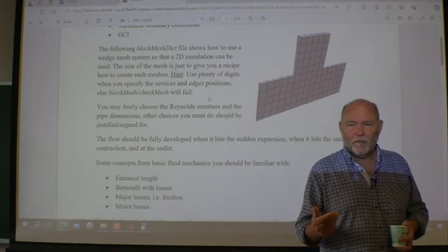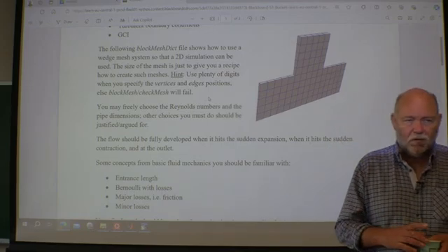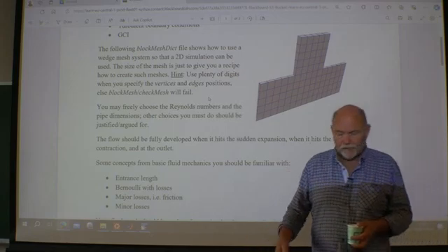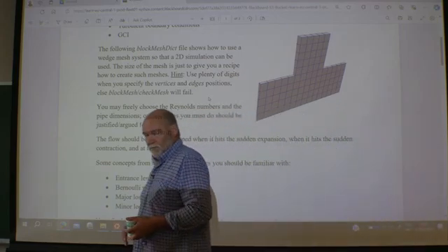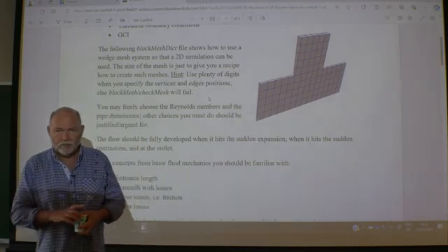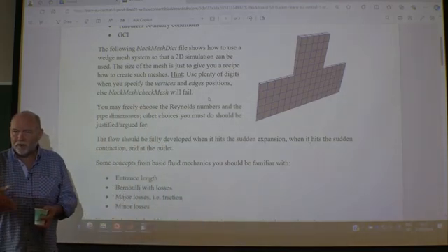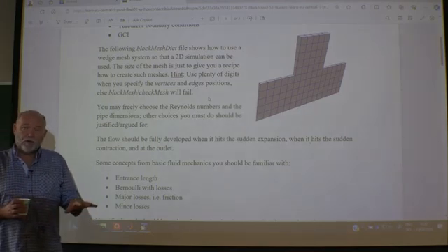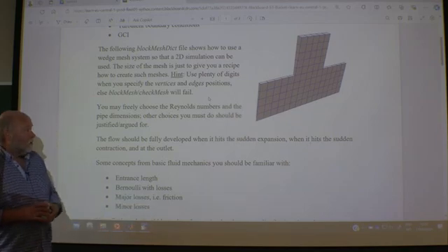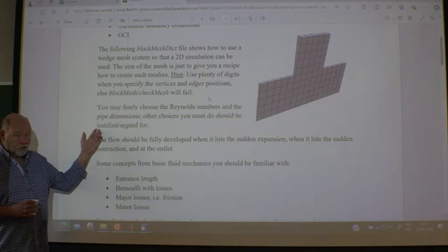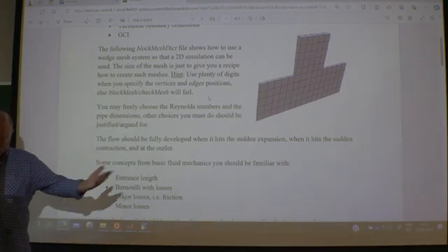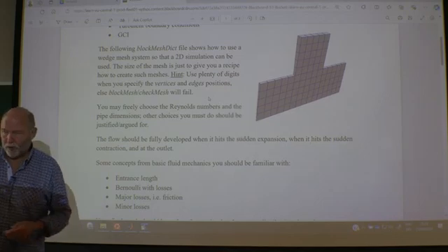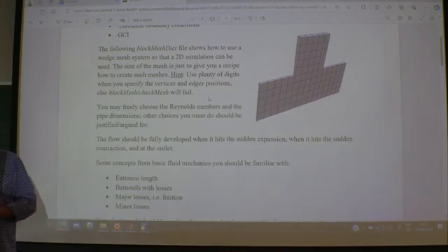Why have you made this choice, like what turbulence models to use? You have to argue all the time that we did it like this because of so and so. It must be justified. You can't just say, okay, we have one setup for a simulation, done. You have to argue for all your choices for the setup.